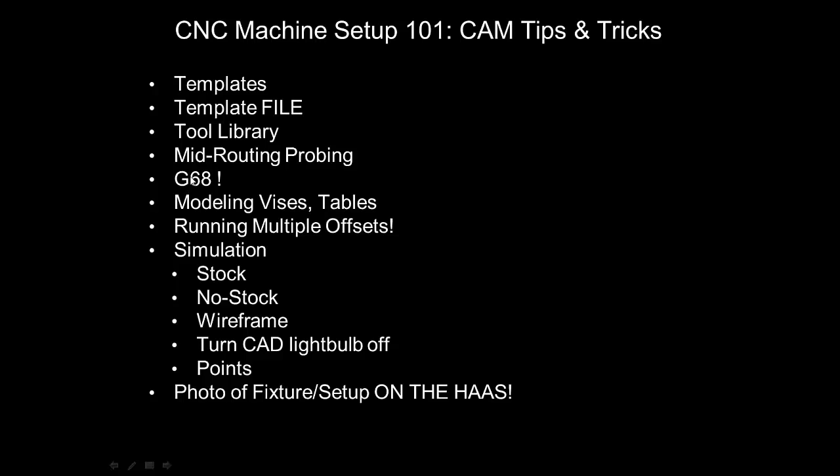G68 is something that's become really important to us, which has to do with how we're holding some of our parts that we're really trying to hold tight to tolerances on. And I'm realizing that tramming each part in, even if your vise is perfect and soft jaws are perfect, I find that there may be some amount of error, 4 thousandths or 5 thousandths across 20 inches.